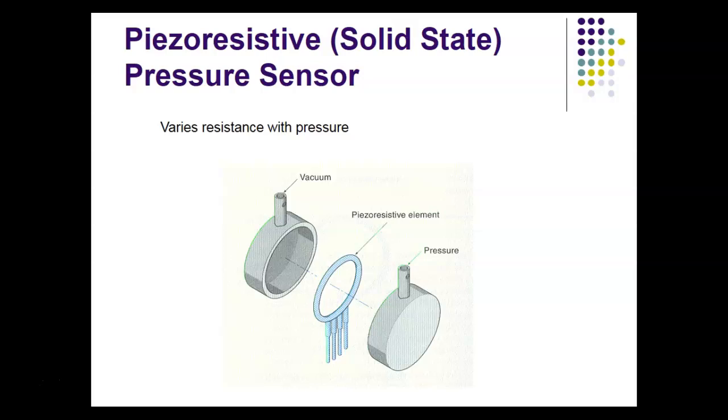I've got one up here somewhere. This came off a compressor. And this has a span set in it. For normal household compressors, we usually let them charge their tanks up to around 100 psi, and then we cut them back on at 70 psi.